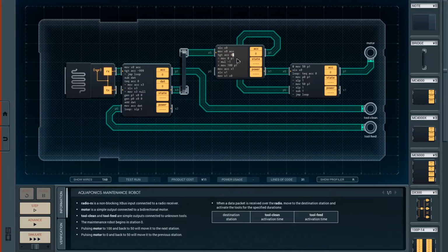If it's greater than 0, then set that pin, which is going to go onto the motor, to 0, and invert this. Otherwise, set that pin to that instruction. Move what is now the number of times the motor needs to be pulsed into there. Wait until it has a result, and shuffle that result onto here, telling you that everybody's job is done.